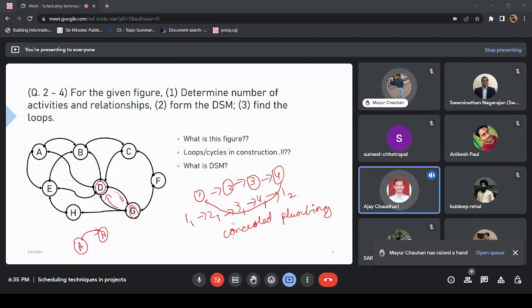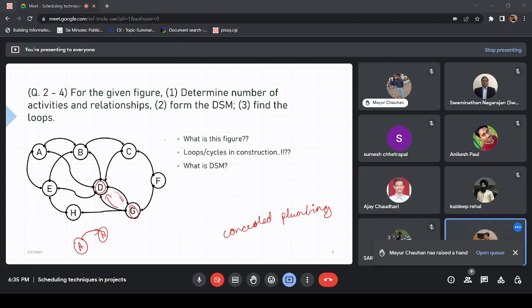Yes. Before plumbing, we have to plaster the wall surface. Then we have to make the groove. Then insert the pipe, fix it, and again we need to plaster it, patch it up before going to the next work. So plastering work is repetitive. First we plaster, then we insert the pipe, and again we have to make it clear so that the plaster will match with each other. And then only we can go for the tiling work. So there is a sequential operation between plastering and plumbing. Sir, you also gave the right word here, sequential.